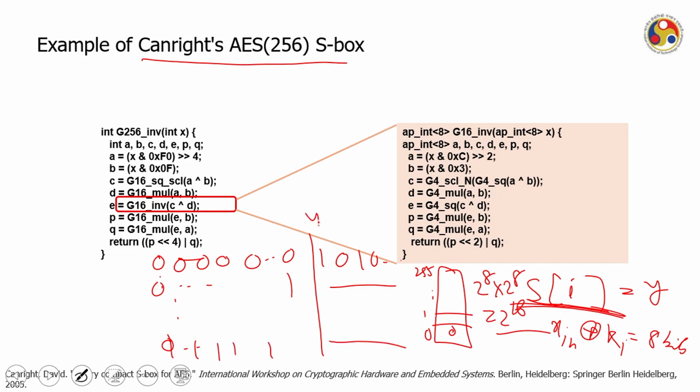So now this is my y0, y1, y2 and so on, and just like your Karnaugh map minimization, I can identify what is y0 in terms of x0, x1 to x7, and what is y1. I am just giving you the idea that although it is a fixed value, I can represent this as a function, y0 is a function of this, y1 is a function of this, and then I do not need the memory.